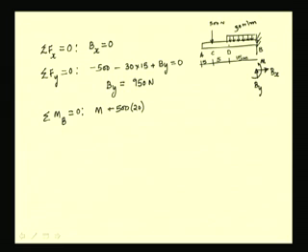Then we have the moment of this distributed force. The equivalent force is the total load acting through its centroid. So here in this case, the centroid lies midway from D to B, that is at 7.5 meters from B. So we have the moment as 30 into 15, which is the total load, and whose moment arm is 15 by 2.